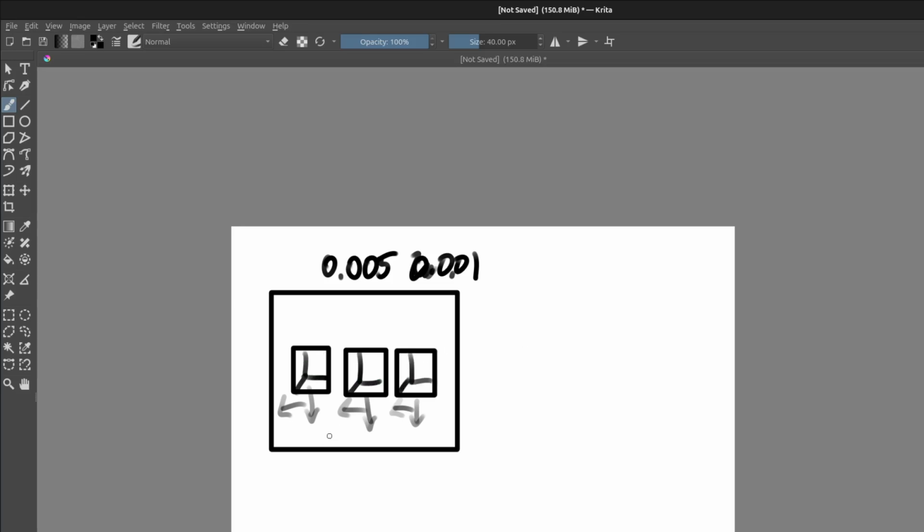And then the way cavities for molding work is we normally set a bunch of inserts in here that are all exactly the same. And our part is, again, another square block that fits into this square block. And this has a feature on it, and that feature is critical. So we've got three of these. And each one of these critical features with respect to its own edge is shifted left or right, up and down.